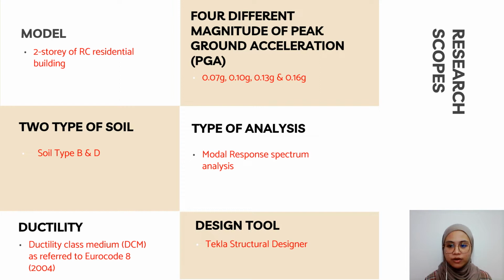These are the scopes of work for this study. A two-story RC residential building is used as a basic model. There are two parameters involved, which are the peak ground acceleration and type of soil. The type of analysis used is modal response spectrum analysis, with ductility class medium as referred to in Eurocode 8, and lastly, the design tool used is Tekla Structural Designer.